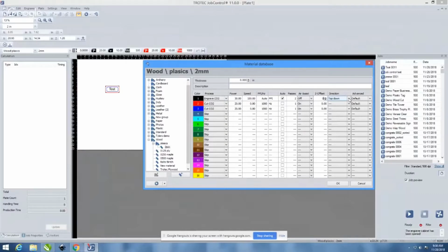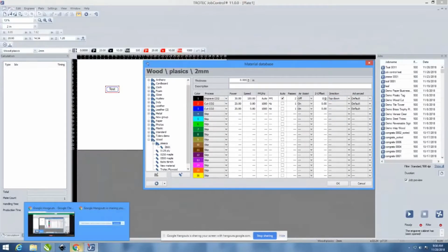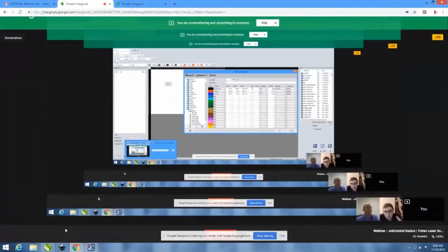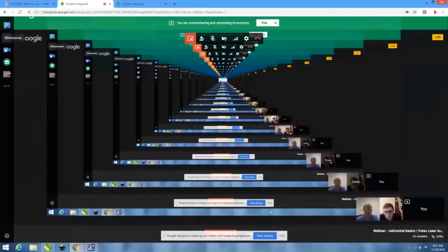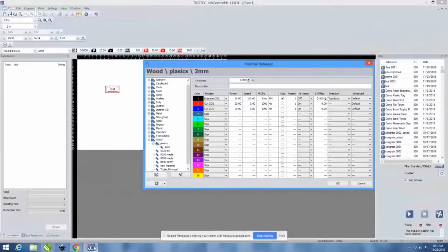But if you want to have a clear engraving, for example, if you're doing a trophy or a plaque, and you're reverse engraving on the back of the acrylic, and you want to put like a rub and buff or acrylic paint on the back, if you're engraving that in focus, you won't see the paint on the other side. You want to have a clear engraving, so you'll take it out of focus.